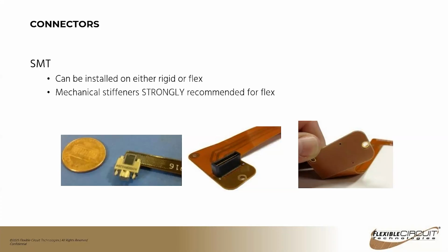These connectors are relatively inexpensive. Mechanical stiffeners are strongly recommended for a flex circuit. So if you look at the image on the far right there, you can see where there's been an FR4 stiffener laminated on, and then the picture in the middle shows a surface mount connector that's been soldered in place.